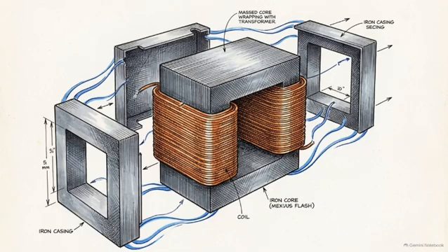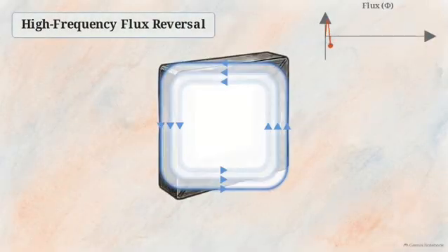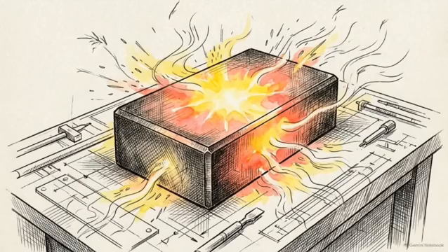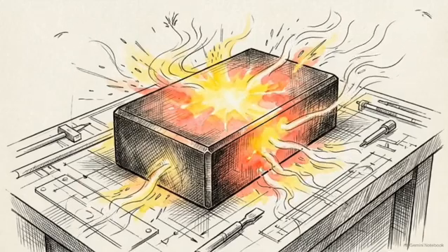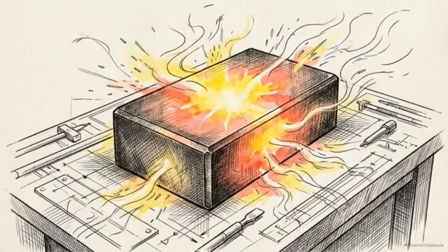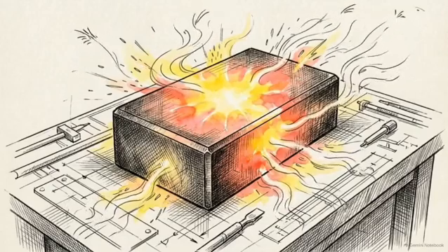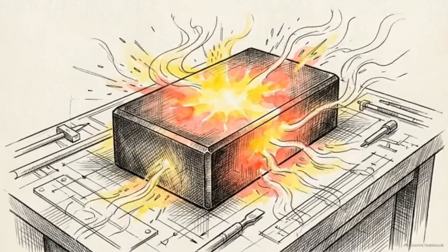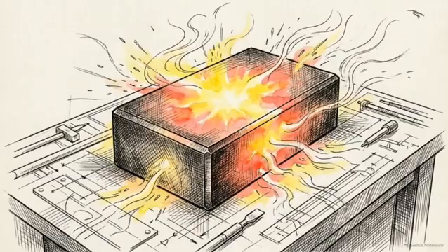They rely on massive bulk iron cores that are subjected to continuous alternating currents, meaning the magnetic flux inside the metal is changing rapidly and constantly. Unmitigated, that changing flux induces massive, unrestricted eddy currents inside the bulk core. The resulting heat quickly triggers thermal runaway, compromising the core's structural integrity.